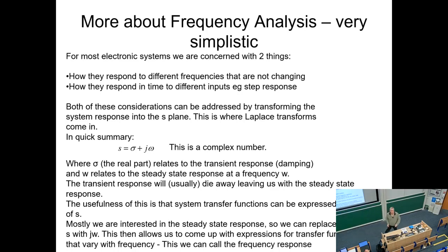Okay, and this is all defined by what's going on in this kind of expression here, which is the solution to differential equations. This is the exponential bit of the e to the whatever solution in the differential equation solved. Okay, so that's what we're looking at. If we want to look at a whole system, we've got to look at this S parameter, which encompasses a steady state response in one direction, and the transient response in the other direction. And this allows us to draw all kinds of clever pictures that allow us to get an easy snapshot of what our system is likely to do.